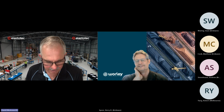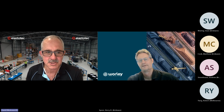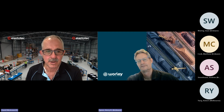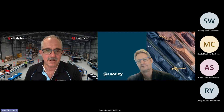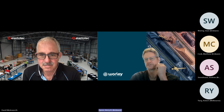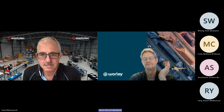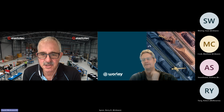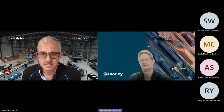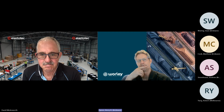The difficult thing is when you start to put all this stuff together, you see belt cleaning is so important. The abrasion resistance of the covers is really, really important. What you do with the lagging is important, because they all interact with each other. And if everything's on the limit, this is what's got my interest now. If everything is on the limit, you really haven't got any kind of leeway for when the belt gets worn. So when the belt gets worn, all these factors are now past critical, and you're just chasing your tail, like the maintenance guys are just chasing their tail. There's nothing you can do. Yeah. Interesting. Yeah, a new thing to consider.